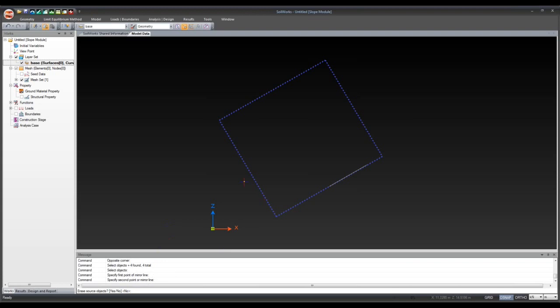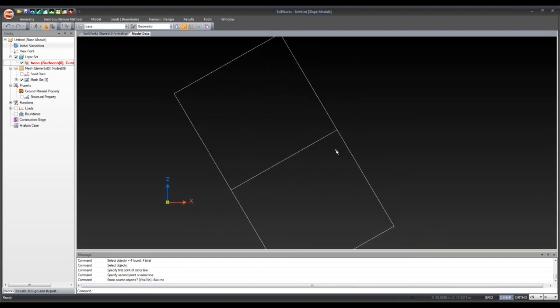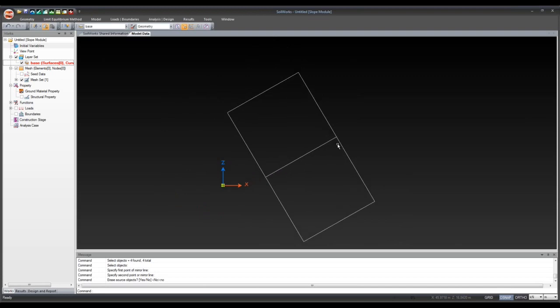And then this one gives you the option to delete your original object. So let's now say, for example, I don't want to, so click no. So now I can create different variations or different mirror images of a geometry I've already created. It's very similar to the rotate option, just depending on how exactly you want to create your mirror image, you'd either use mirror or rotate.